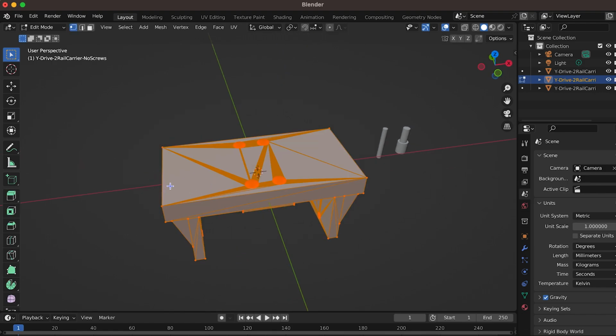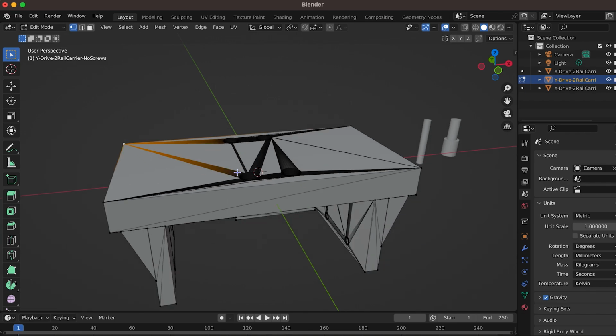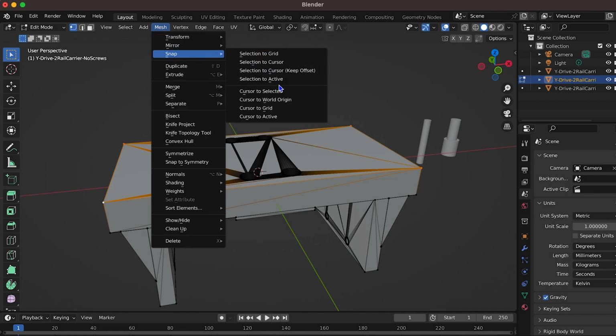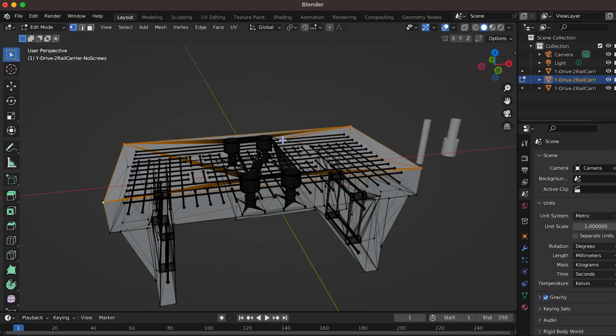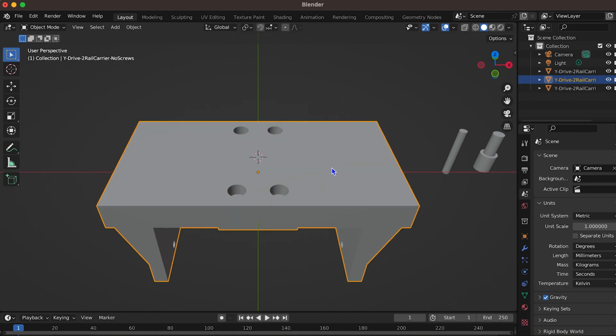First of all, we are pressing Tab to select the STL vertices, and then I'm going to select these outside edges. I did not round those edges by 45 degrees because I just want you to have a very simple job in selecting those edges. After I select them, I go to my mesh and snap my cursor to selected. Oh, the cursor moved a little bit up, yes. What it does is set the cursor into the middle of those four points, which is the middle of my big carrier object, right? So I'm leaving that now. This cursor is a very important thing.